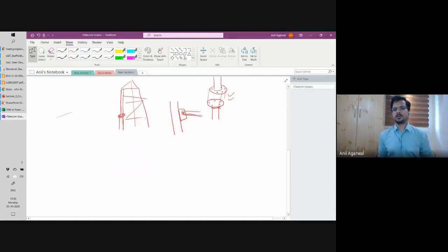Alternatively, what they do is, they again put a gusset plate, weld it, and instead of an angle, they bring another tube. But at the ends, the tube is crimped, okay? So it becomes flatter and wider, and then bolted. So this kind of crimped ends are useful, or can be used, only in case of members which are not a very large size and they have enough ductility, or small deformations only. So this kind of arrangement can be done.